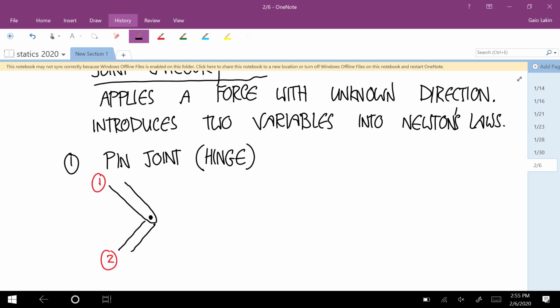There's no direction that you can translate it. So that means choose your first axis, there's a force in that direction. Choose an axis perpendicular to that, there's a force in that direction. So you can think of that as an unknown force vector. There's a full vector of unknown forces that limits that motion. What about rotations now? Yeah, I can rotate it freely. And so there's going to be an unknown force vector, but no couple.